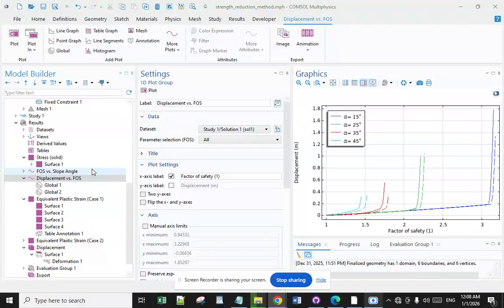Margin of safety as a measure of structural capability. This definition of margin of safety, commonly seen in textbooks, describes with an additional load beyond the designed load, a part can be withstood before failing. In effect, this is a measure of excess capability. If the margin is zero, the part will not take any additional load before it fails. If it is 1, it can withstand one additional load of equal force to the maximum load it was designed to support, for example, twice the design load.